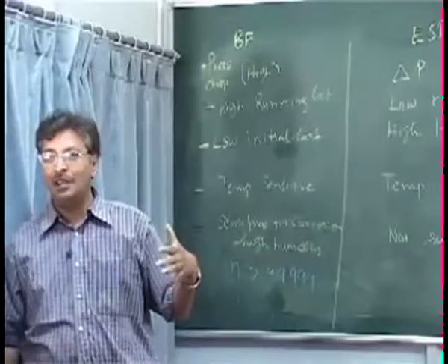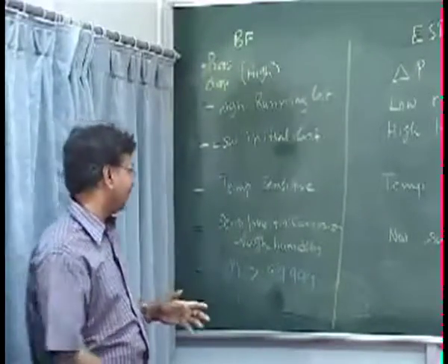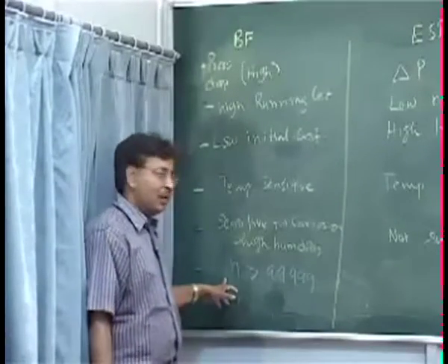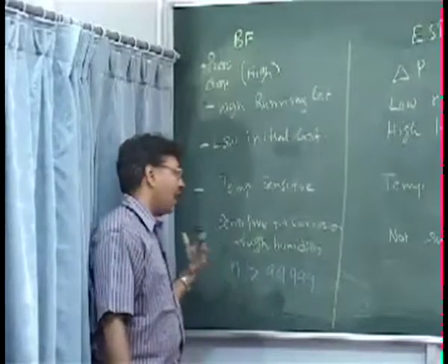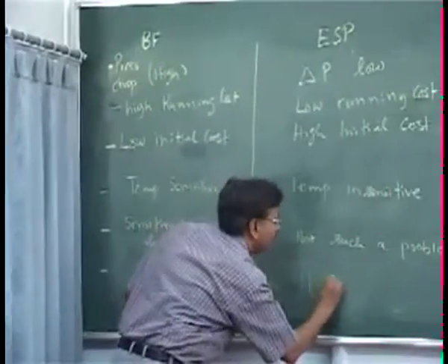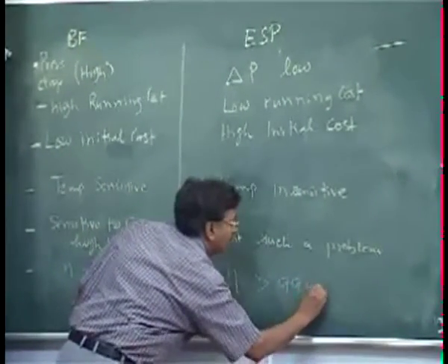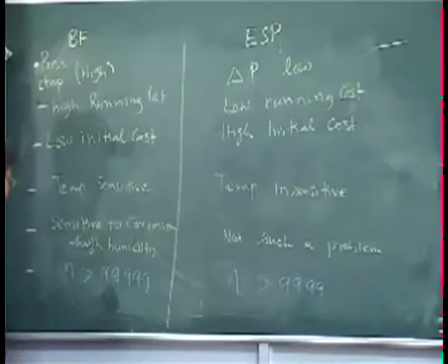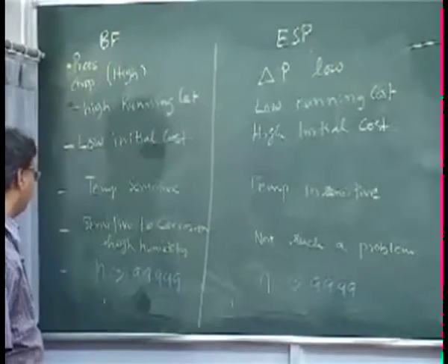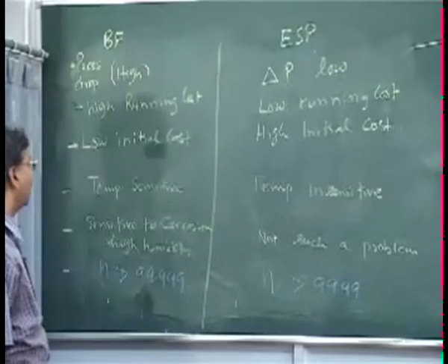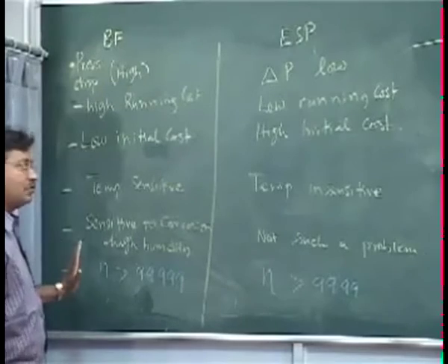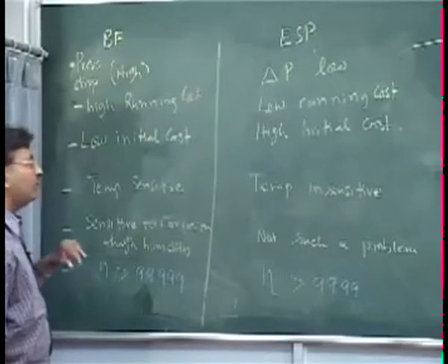I am just giving you an example which is a very coarse example, but for example, cement industry, because cement is a product, okay, so then they will have this one, because the efficiency of the bag filter is high. Efficiency here is also high, of the order of about 99%. Okay. So they both are comparable, you see here, but depending on what situation you are in, you have to use this one.